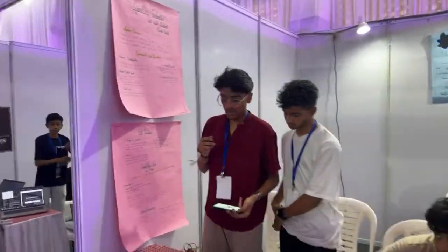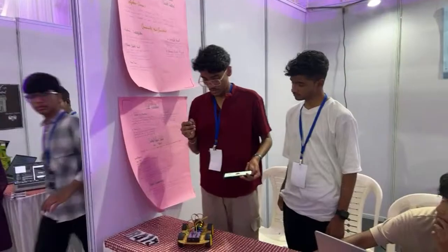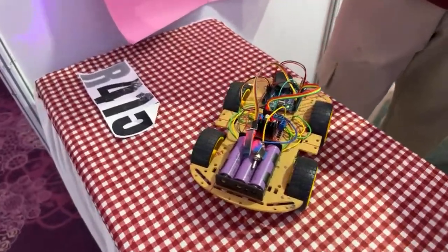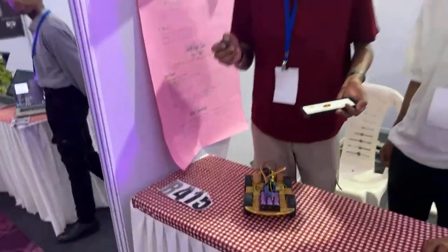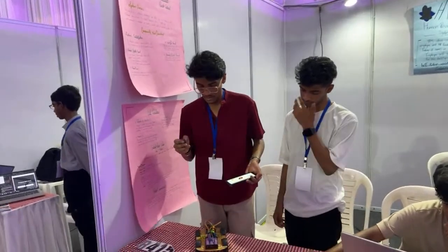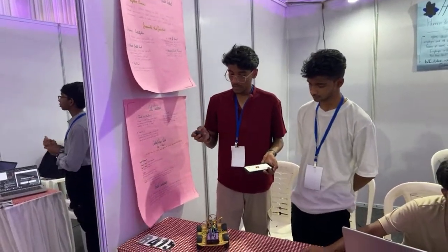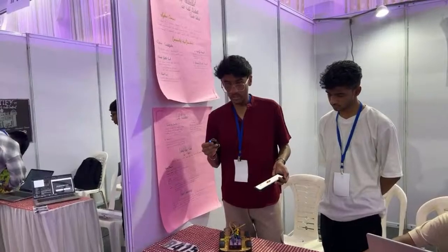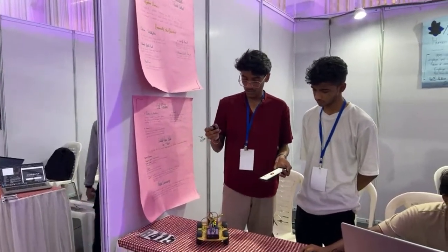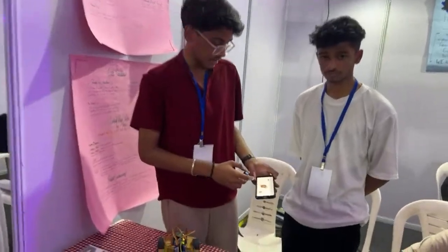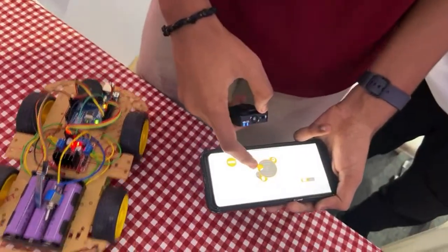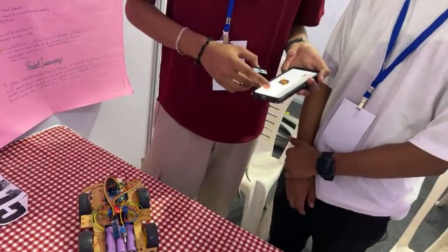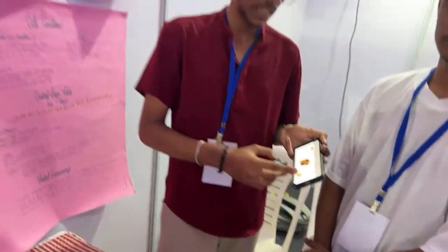So we are here to present our gesture control plan. We have used an Arduino along with the L298 motor driver and 3 lithium-ion batteries, which are connected in series, which output a total voltage of 12.4 volts. And both of them give us a capacity of 1200 milliamp hours. We have used PWM, pulse width modulation technology, to control the speed of the motors. So we can control it using our phone. We have also added a horn functionality, which uses a buzzer to produce sound when clicked.